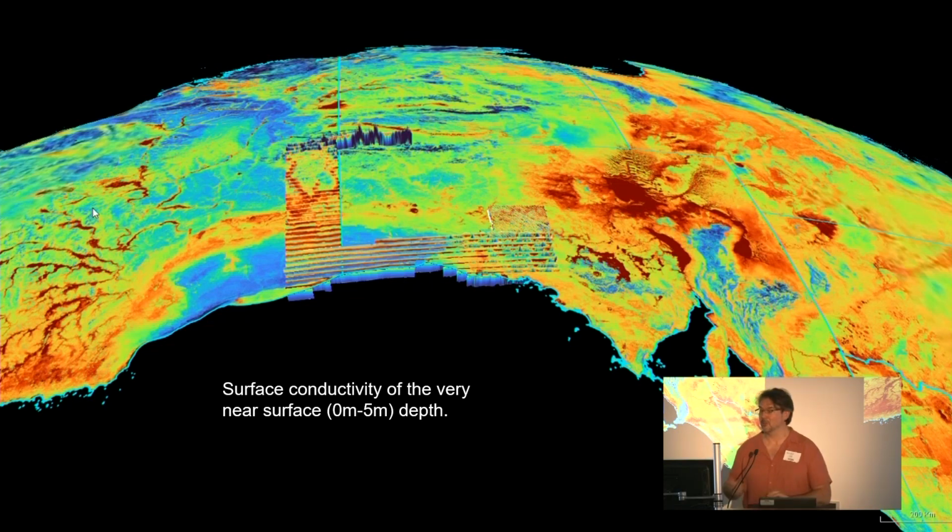I'm quite skeptical. This is a grid of conductivity of the near surface where we fed, I know exactly what we fed the algorithm to train the data sets. And the main driver is the conductivity of the AEM, the very near surface. It's a beautiful image. You can see it's being guided by radiometrics, satellite, DMs. So what we're trying is to fill in the gaps between those flight lines. All right? So it's a trained interpolation, let's say.